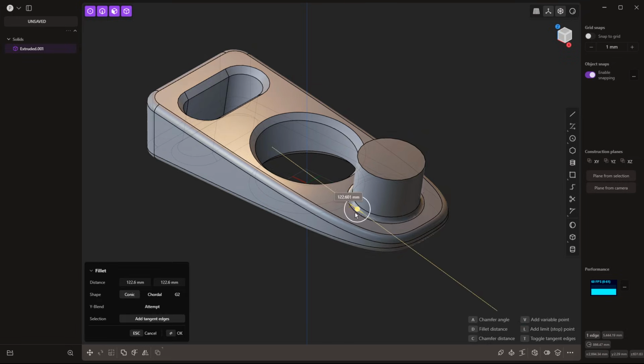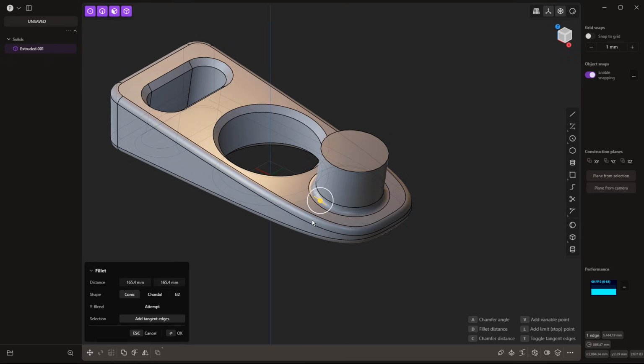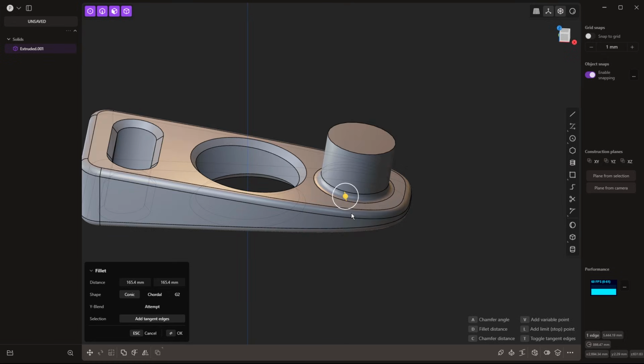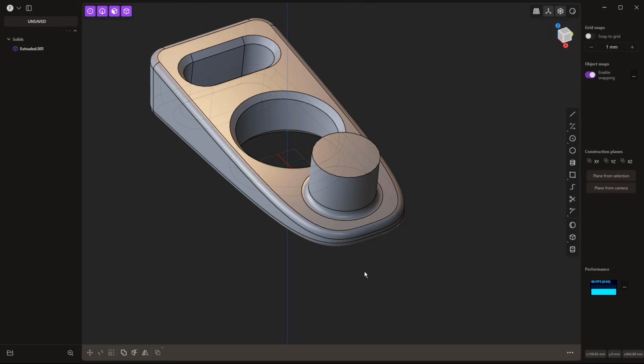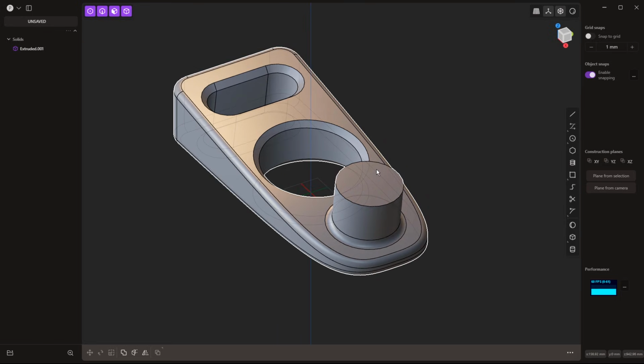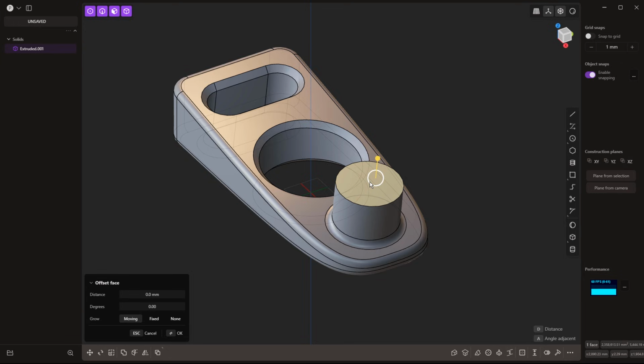If we don't have a single body, when we try to do something like fillet that edge, you'll notice that it rounds itself under instead of over. Now, a lot of times when we're modeling, adding a construction plane, then adding a curve is not the most efficient way. So there's a couple other ways that we can use these direct modeling tools. For example, we can select this top face, we can hit O for offset, begin offsetting that inward, right click to accept, and then pull this down through the model.